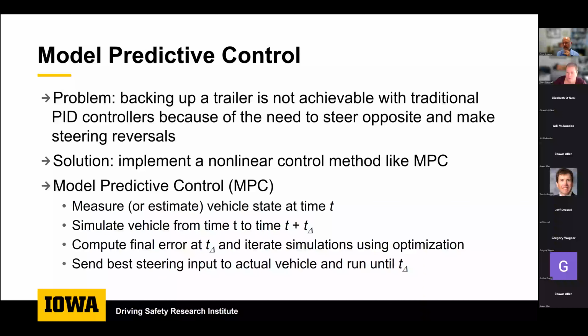So you can basically make a guess or several guesses and simulate what the motion of that car and trailer would be for a short time period, maybe half a second to a second. And then at the end of the simulation, you measure where its predicted movement would take it, and you give that final position a score, or you could calculate its error, okay? Like error in the lane. And then if you do that for 100 guesses, you just use the one that has the smallest error.